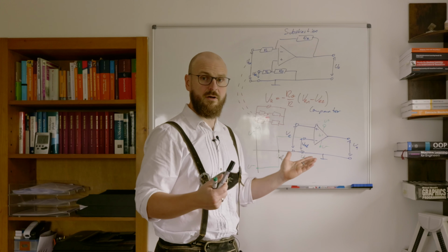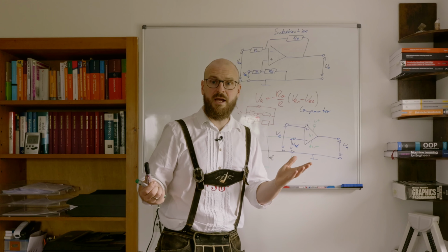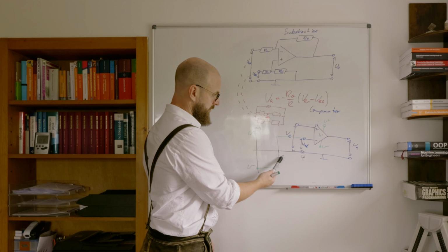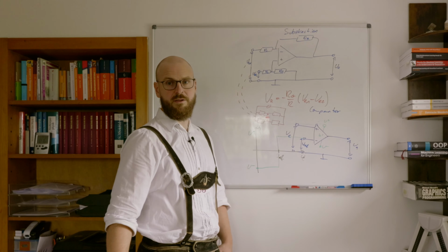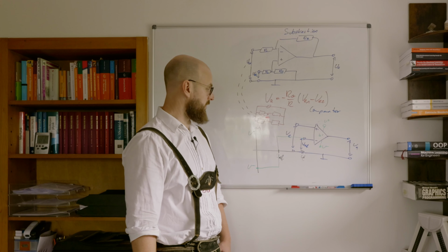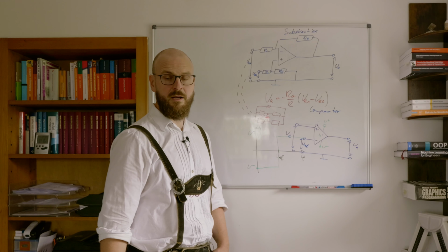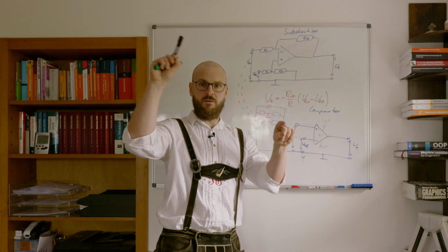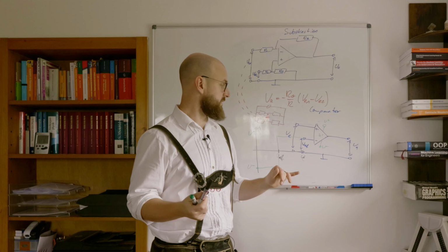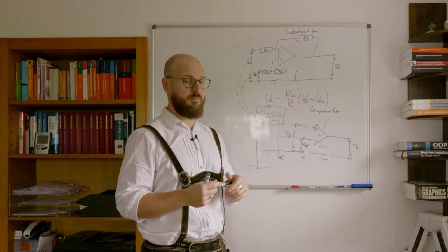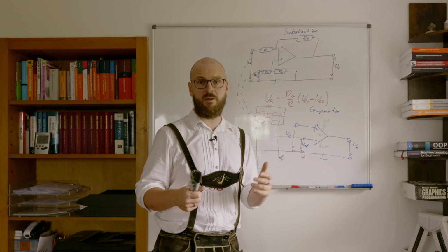What is that used for? It's digitizing signals. That thing allows you to compare the reference voltage to the input voltage. That's what it's all about. You know when you're smaller than the reference voltage, you know when you're bigger, and you get a zero-one signal, a digital signal at the output of the comparator. That's why it's called a comparator, because you can compare two voltages.